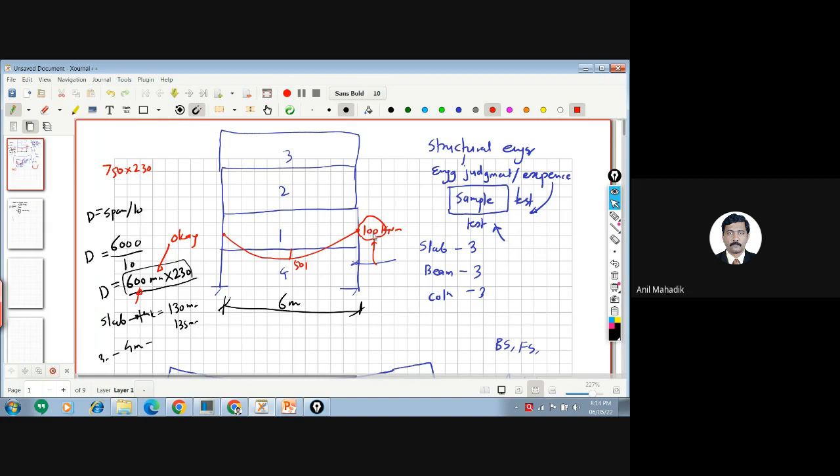You will design this for 100 and it is okay, but you had previously assumed 600 mm and calculated the dead loads using this, and now you are increasing the size. That means the dead load will also increase, which means the bending moment will also increase. So in general, in this case, we go again for the analysis. I have analyzed by assuming certain sizes, and if I feel the sizes are less, I need to increase them. First increase the size and check the design.